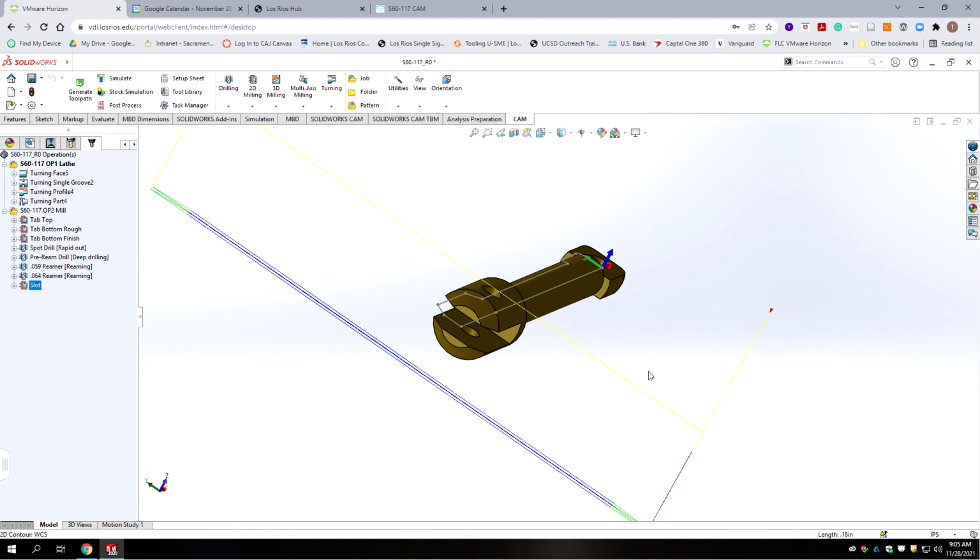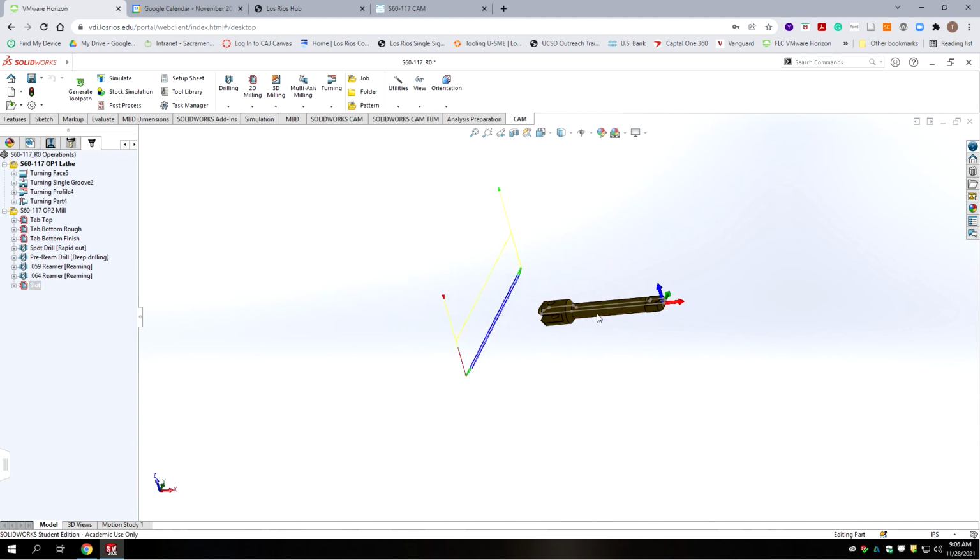There we go. We've just programmed the 117 by recycling. Hopefully you didn't get too lost on here. Hopefully the labeling I've put on here will help us on the future ones. And we're going to be copying basically these 2 routines to do not only the 143 but the 145. The only difference is we won't be using the slot mill to cut the tabs on the other side, because we can orientate the part so that the flat's facing up.